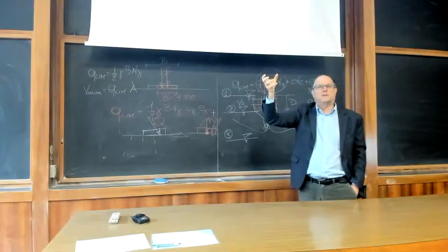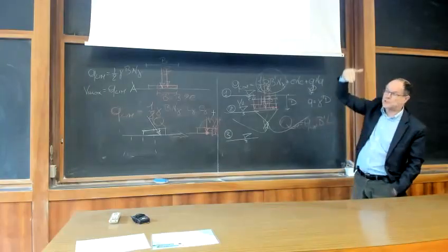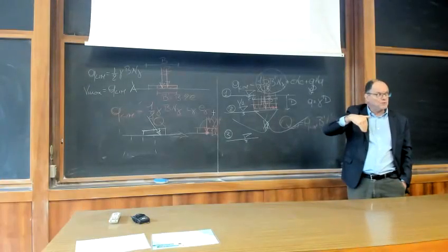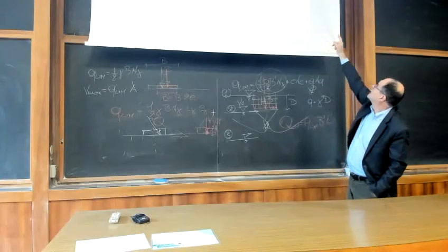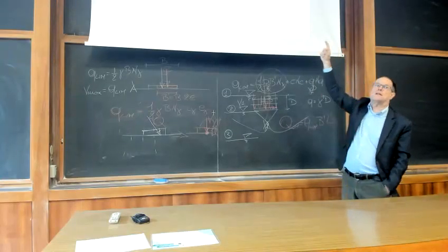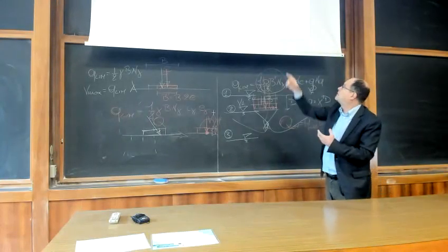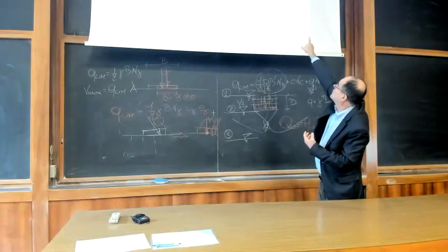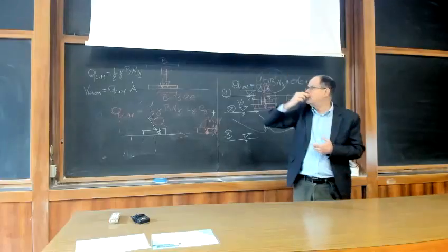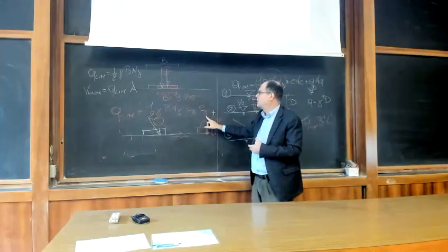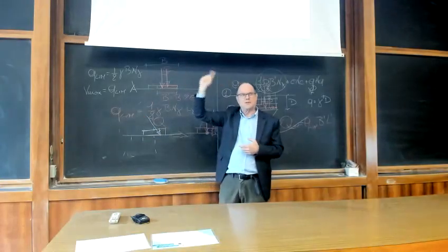They act together. Whereas on the right-hand side, you have the same inclination, same eccentricity, but on the other side, opposites. And so the eccentricity and the inclination act together in a different way. They combine and provide you with a capacity which can be twice as much as the other capacity. Now, if you use this expression, you end up with something which is irrespective of the direction of the eccentricity.